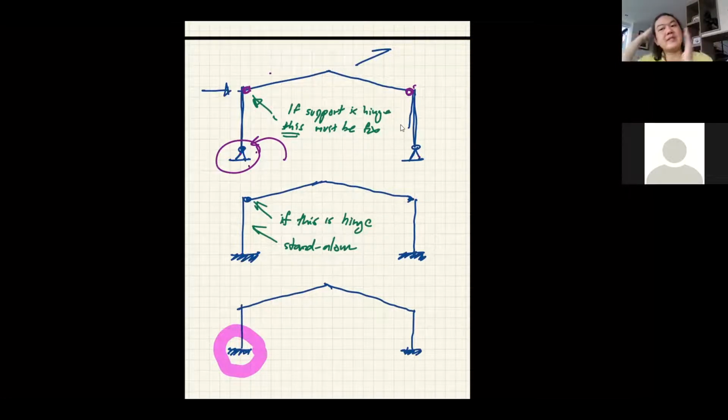So now, what you have always learned in the analysis class, mechanics of materials, when you draw a support, a roller, a hinge, and a fix. Now it comes a time when you must start to learn how you can achieve that kind of behavior. So this is the fun part of being an engineer, really, okay? Because you control the behavior. When you perform the analysis, you say, this is what I want, I want this kind of behavior out of the structure. After the analysis, you've got all the forces in the members and so on. You must know how to make all the assumptions you make in the analysis become reality. So that's why we are taking the design classes, to make sure how we can achieve the behavior that we want.